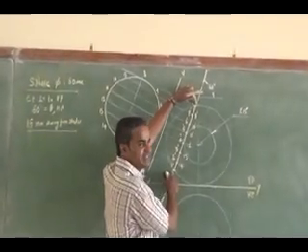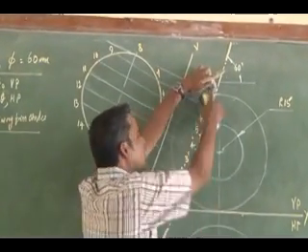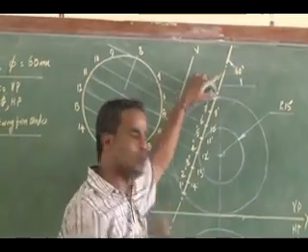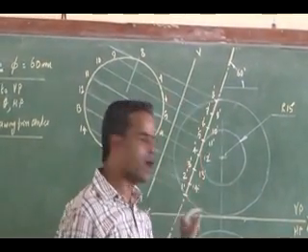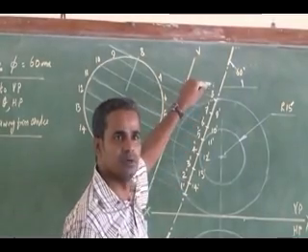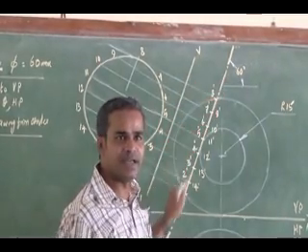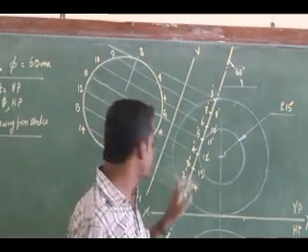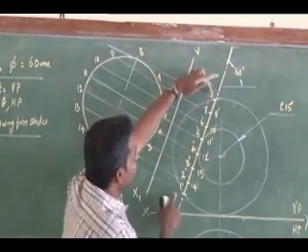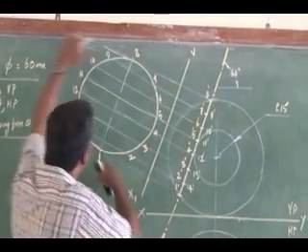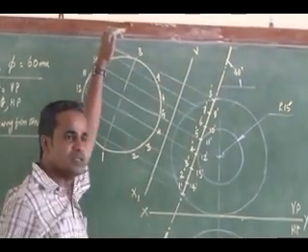Cutting plane within these extreme cutting points. Okay, you can mark any arbitrary location to show your cutting points. Right? Is it clear? So any arbitrary location you can mark. Then you number the cutting points, name them. Okay, visible and hidden cutting points in an order you name them. So using 1 and 8 distance and diameter, already you have drawn the true shape.